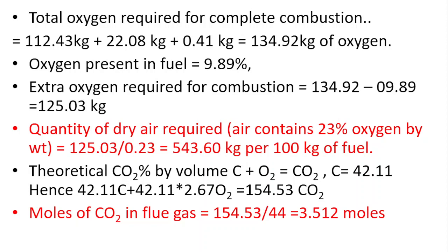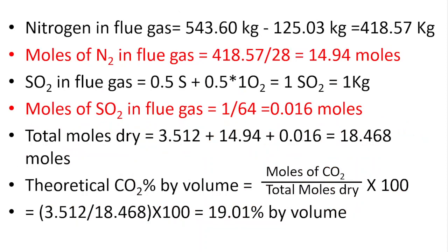So the theoretical CO2 produced by volume, C plus O2 is equal to CO2, will be around 154.53 kg CO2. So the moles of CO2 in flue gas would be 3.512 moles. Similarly, nitrogen in the flue gas is calculated, and moles of nitrogen in the flue gas will be around 14.94 moles. Similarly, moles of SO2 in flue gas will be around 0.016 moles. So total moles can be calculated, and they come out to be around 18.468 moles.